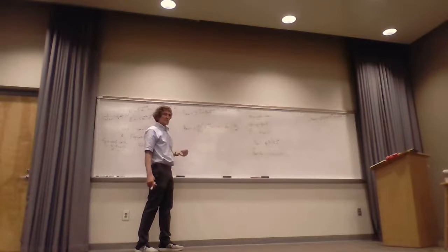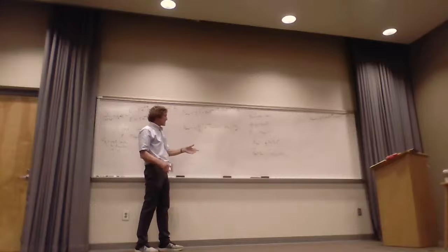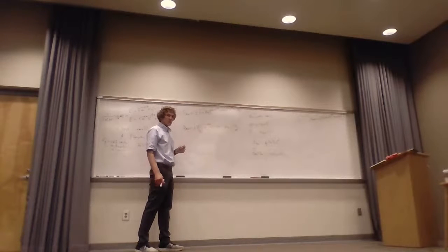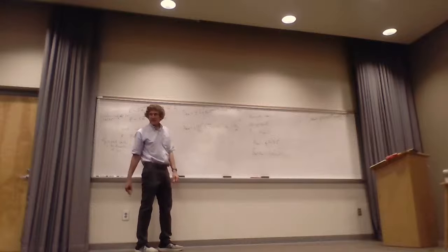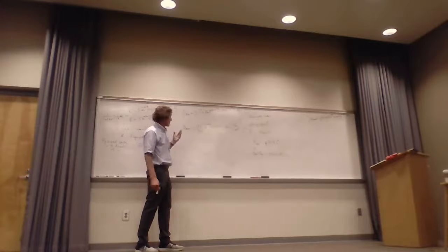So the worst case, when it's 45 degrees, that's a really good conductor. The cosine of 45 is 1 over the square root of 2. So that's the range. Follow me on that? It's not terrible, but it's enough that you have to pay attention to it. The main power loss always comes with e to the minus 2 alpha z. That's where the thing just decays down to 0. But that is the power flowing in a propagating wave.